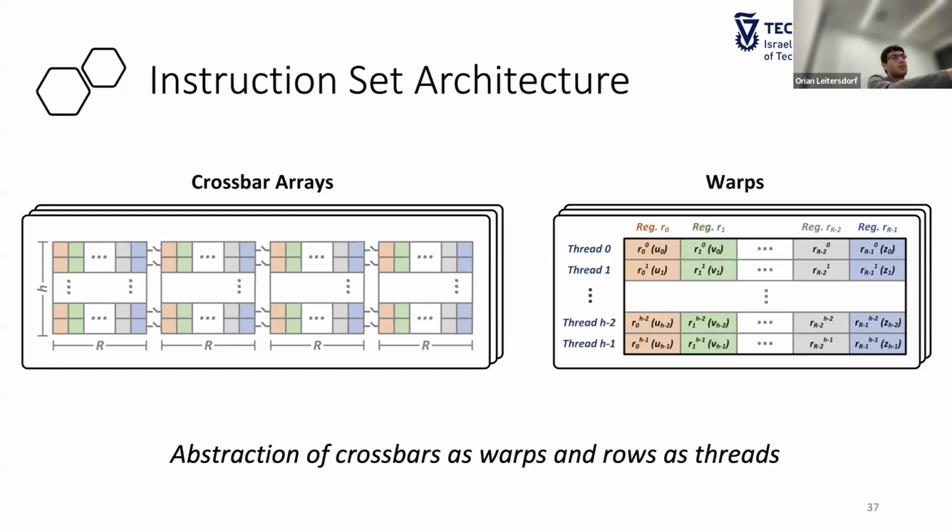So for example, if our crossbar array had 1024 columns, so 32 32-bit numbers, here we're going to represent that with 32 32-bit registers. And the interesting part here is that on the one hand, from a parallelism compute perspective, it's similar to CUDA. You're operating with all the threads performing the same operation. You have to operate in lockstep. On the other hand, the warps are the memory. Let me emphasize that a bit more.